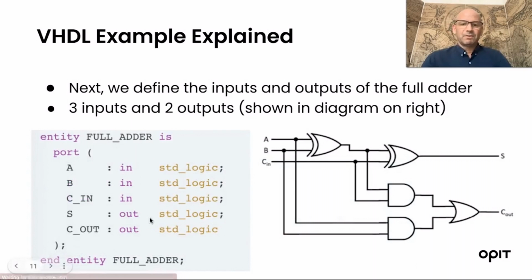Let's go back to the previous slide. If we look at that logic and we apply it here, you can see that A and B indeed are XORed. So here's our XOR gate. And then the output of A and B is then XORed here with C. And that gives us the output of S. Then we can apply the same rule set to the output of C out.